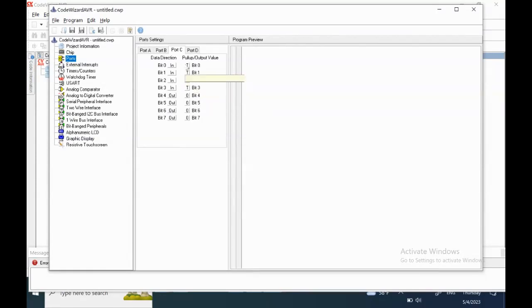These options here, as you see, for the first 4 bits, bit 0, 1, 2, 3, give such an opportunity. As you remember, we used the PORT register for activating the pull-up resistor when the bits of one port are configured as input.